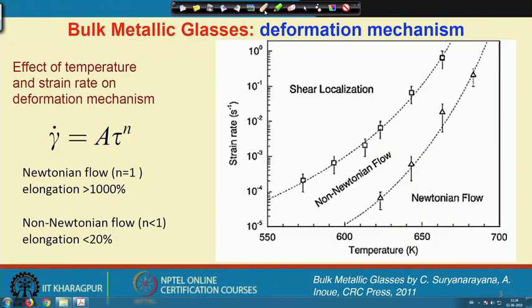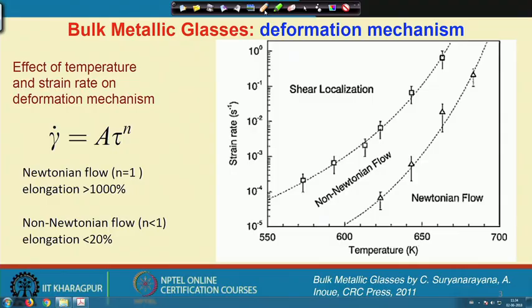And a shear strain rate that is applied to a solid, however, a strain rate that is generated inside those atomic clusters, which may not be the same as the imposed strain rate. And along this direction, if we simply take a supercooled liquid, even though the viscosity is higher than the conventional liquid, a supercooled liquid has a higher viscosity level than the conventional liquid, but we can think about a Newtonian or non-Newtonian type of flow.